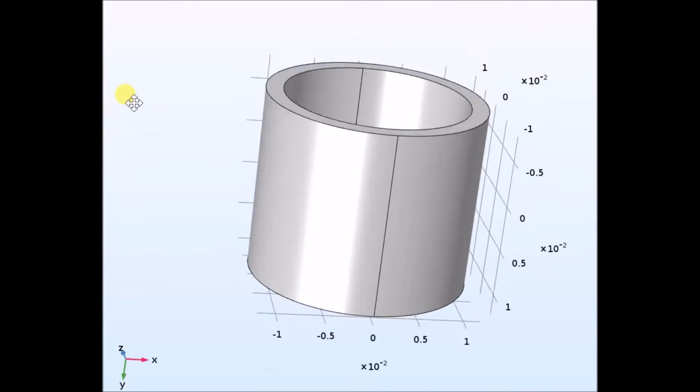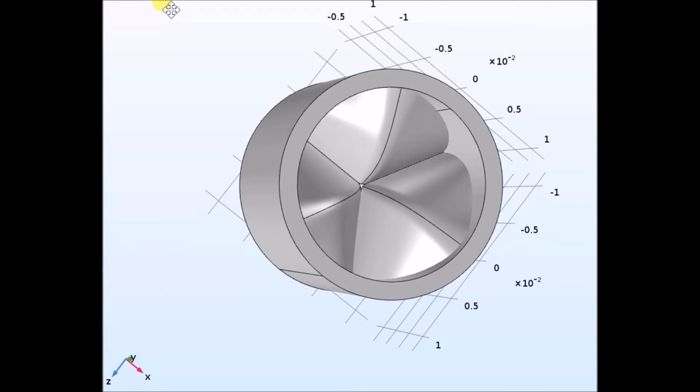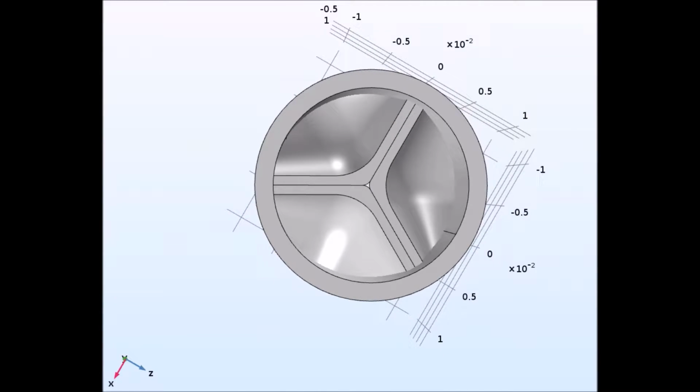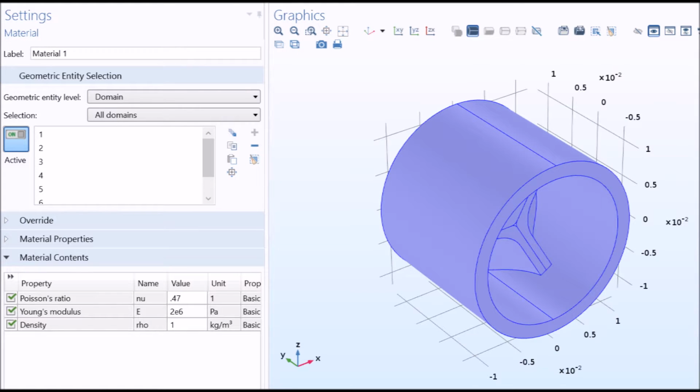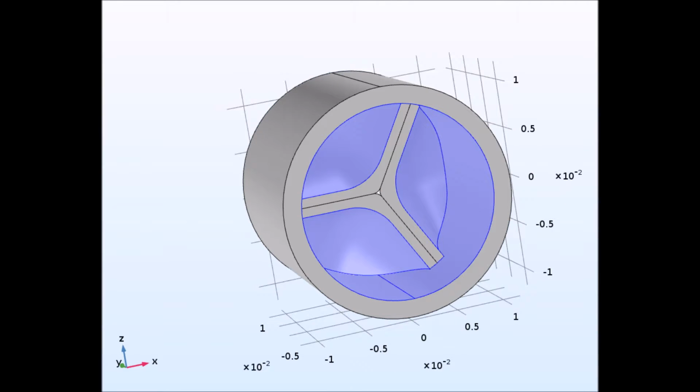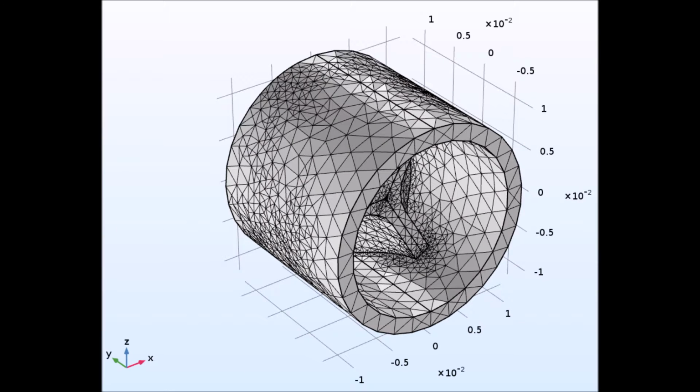In COMSOL, we selected the 3D model, solid mechanics, and stationary study options before importing the SolidWorks part file into the geometry node. Assuming simplified isotropic valve behavior, the radial Young's modulus and Poisson's ratio were input in the materials node. The vessel openings parallel to the annulus plane were fixed to keep the valve in place for the applied load, and a transvalvular diastolic pressure was input on the interior of the leaflet's cup shape and adjacent vessel wall. Finally, a free tetrahedral mesh was formed and refined once before the stationary study was computed.